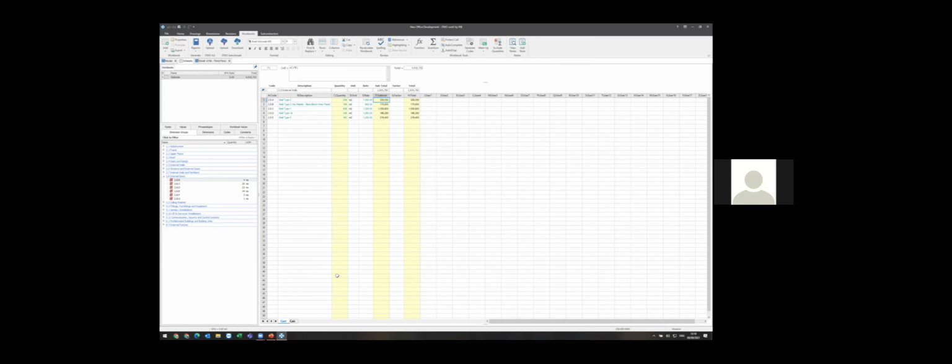The part that a lot of people struggle with, particularly utilizing the BIM workflows, is design maturity. And particularly at early stages when you're producing cost plans, you generally don't have the level of detail within the models to extract all the quantities you need. So it does become a hybrid approach.